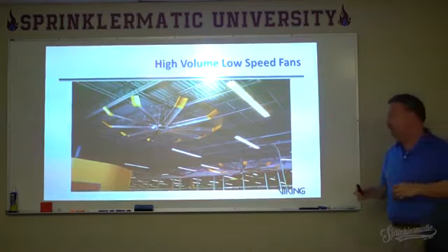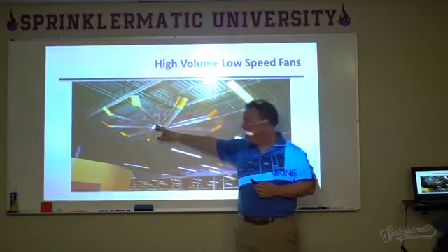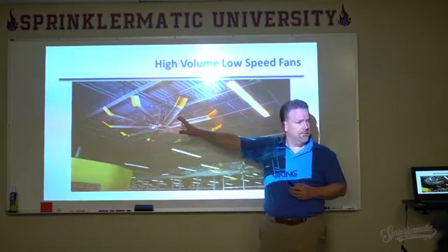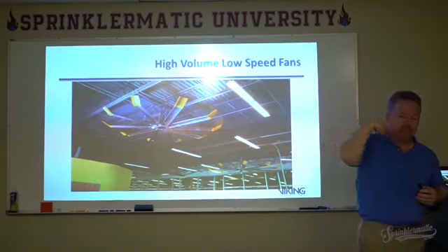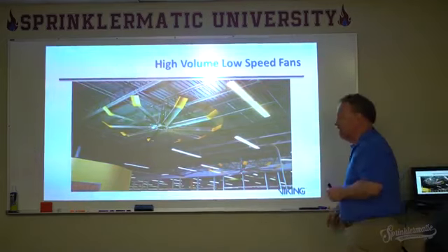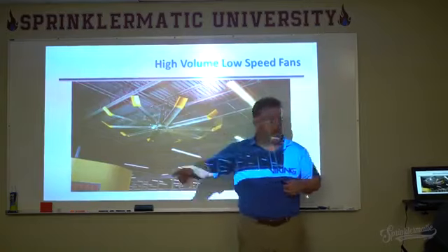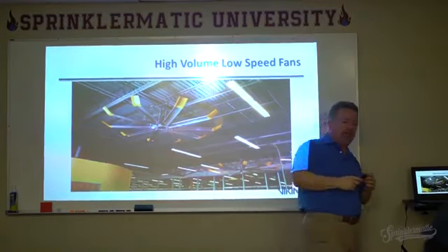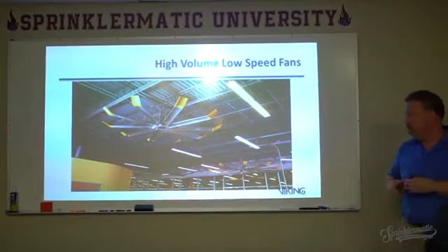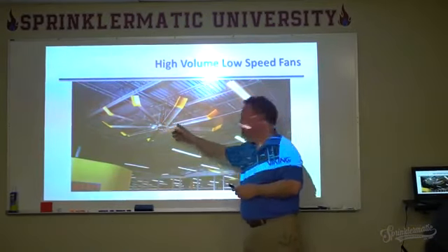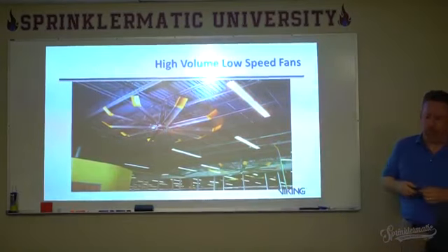As long as basically this item here stops before it shuts down with the alarm. The detection system shuts the fan down. And you have, as far as ESFRs are concerned, spaced equally around that particular unit. We can treat this simply by standard obstruction rules at that particular point.